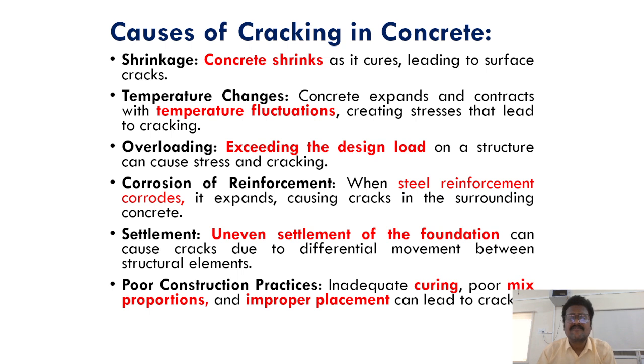What are the causes of cracking in concrete? There are six major reasons. The first one is shrinkage. Concrete shrinks, leading to surface cracks. The second one is temperature changes. Concrete expands and contracts with temperature fluctuations, creating stresses that lead to cracking. That is a natural process.